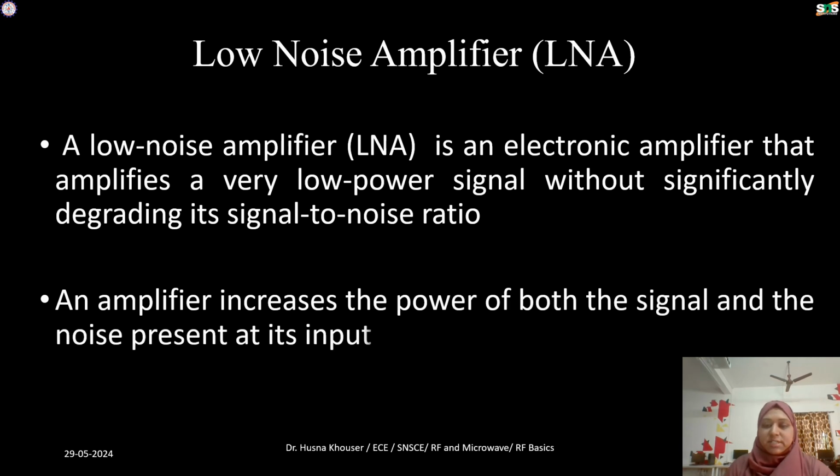If the transmitter is sending the signal, it will get attenuated, that is, the signal power will be reduced due to the outside environment, and when it reaches the receiver, the signal amplitude power level will be reduced. So we need an amplifier to amplify the signal, because our signal will have low power and it's very difficult to recover the data in it. And I'll explain the basic LNA next.